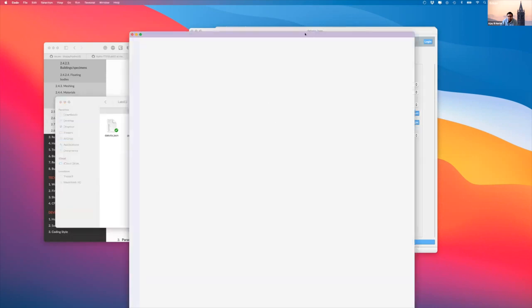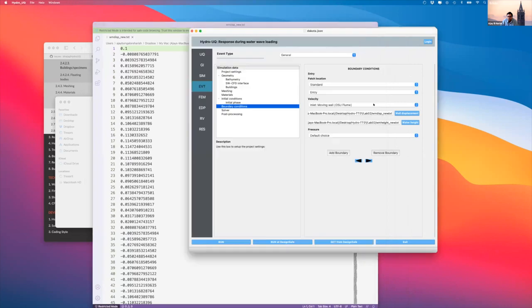So if you're looking at the Oregon State University Flume, then essentially you don't have to do anything. You just bring the file from your experiment, select OSU, and it's done. But probably not everybody might be working with the OSU Flume directly, so you might have files in different formats. So there's also a general Flume, which defines a general, let's say, SimCenter format in which you can give the files to the HydroUQ.